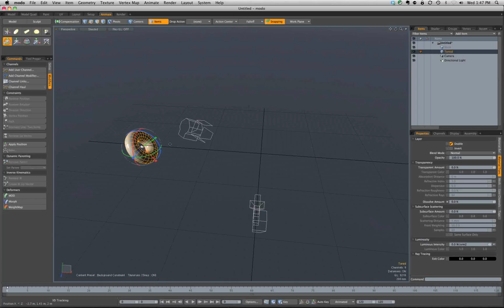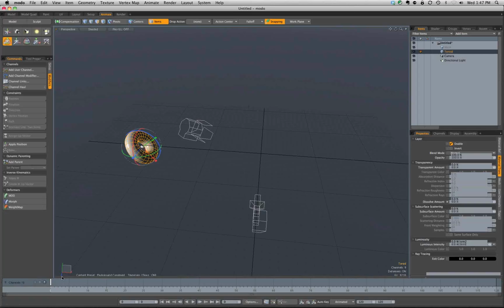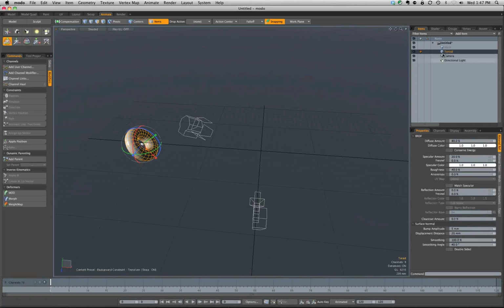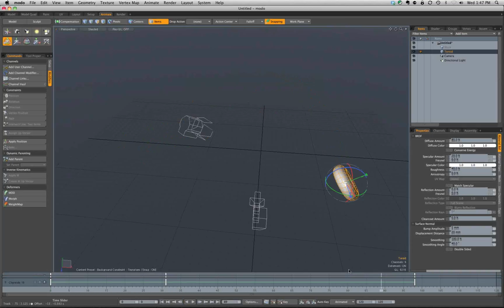So we got our Y, and then I just like to press Shift Y, and that creates a keyframe. Go back here for my properties for all of the keys. And then I can go to the next point in time, and it automatically creates a keyframe for me because my auto key is set to animated. So anything I do will be keyframed. And we'll jump back down over here and move that down.